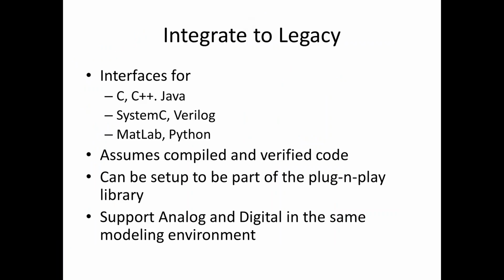Now, before we go into too much detail of the modeling at the graphical level, let's talk a little bit about the legacy. You do have the ability to import code, import your RTL or import your SystemC modules. Plus, you also have the ability to import algorithms that might be written in MATLAB or Python into the model itself. Once they import it, they just behave like just another building block in the environment. Certain restrictions are there in that we assume it's compiled code and it's fully verified code. Once you integrate it, it just becomes part of the library, and you have access to it for all times.